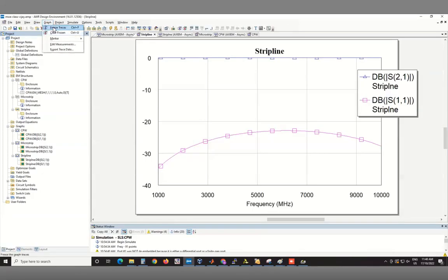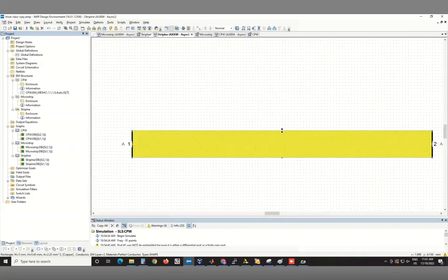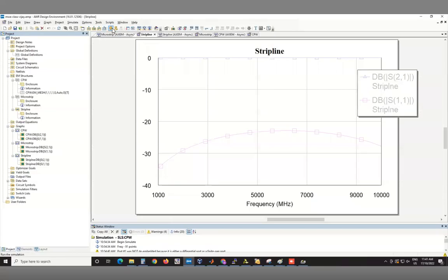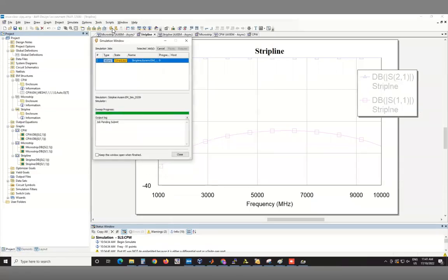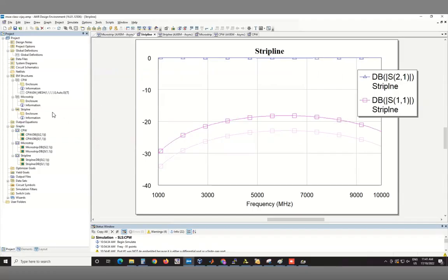And notice this is a smaller length, so you're not seeing the many periods. I increased the length for the microstrip. This one is only 5 millimeters long. So again, this period you're seeing is exactly the same effect. I make the width smaller by 50 microns. It's 400 microns. It's clearly worse.